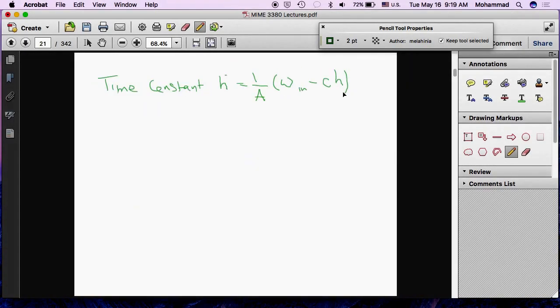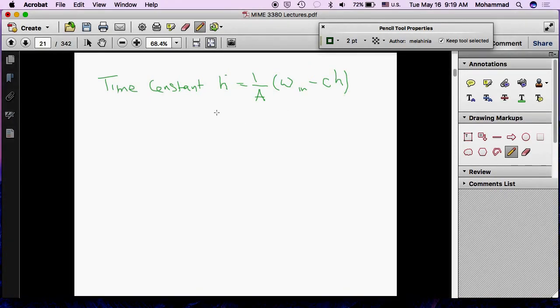So the form that I'm asking you to take your equation to is this. T x dot plus x is equal to U divided by B, where x is state variable and U is input. So what is the time constant for the fluid tank? A over C. So let's give it a try.